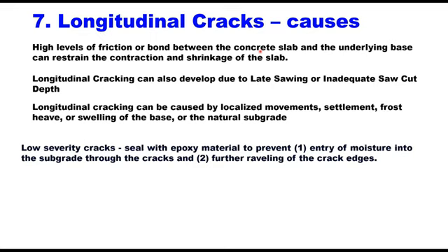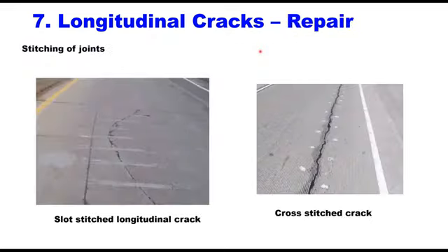Low severity cracks can be sealed with epoxy material to prevent entry of moisture into the subgrade through the cracks and further raveling of the cracked edges. In case of high severity cracks, full depth repair and slab replacement are normally recommended. Cross stitching and slot stitching are alternatives to full depth repair or slab replacement.